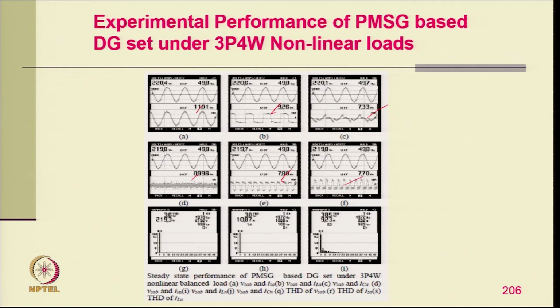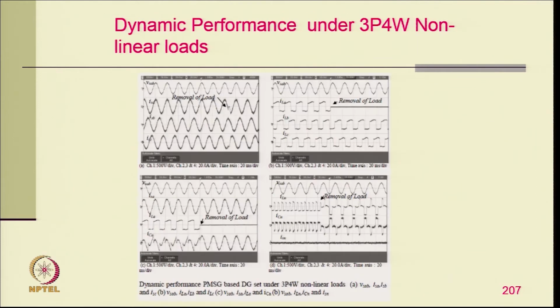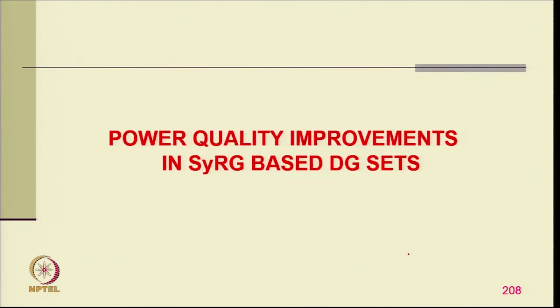each other. So, we have a THD of voltage 3.6%, where the generator current THD is 3%, and the load current THD is 38.5%. Under such a highly non-linear load, it is capable of compensating, and having a very low THD of the terminal voltage of the generator as well as the generator current. So, here with a typical non-linear load and unbalancing, the generator currents are balanced and sinusoidal, and neutral current compensation is also taken care of, and the neutral current of the generator is made 0.